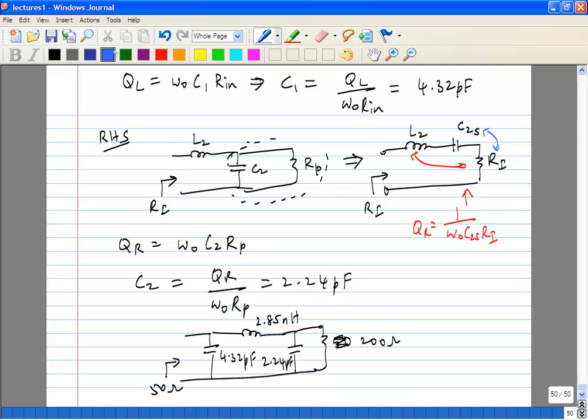The main reason is energy is shifting between the inductor and the capacitor, right? So if you want to find out the total energy stored, you can use the peak energy stored in the inductor. At that time, when you look at the peak energy stored, the capacitor will have zero energy stored. All the energy has moved to the current in the inductor. So that's why those two expressions are equivalent.